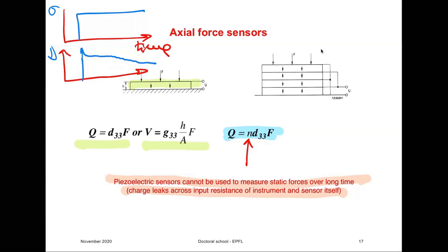So the moment when you apply pressure, you will measure some charge. That charge will remain constant for a while, but let's say after some minutes, half an hour or so, longer in quartz and shorter in ferroelectric materials, it will start drifting. You will start losing that charge, and you would have an impression that the force has been lost while you just have a leakage through your sample.